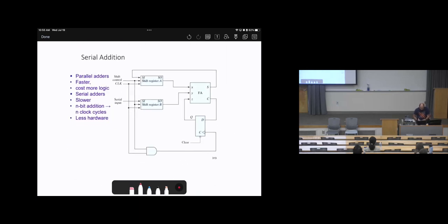Okay, so let's talk about serial addition. If we have 2 registers and you need to make an addition, connect them to full adders. So there are sum and carry bits. Then make sure to store the carry bit in a storage element so it will be updated for the next one. We can use this design to make addition depending on the inputs. So if we have this input, next clock cycle make addition, the other clock cycle make addition, and so on.